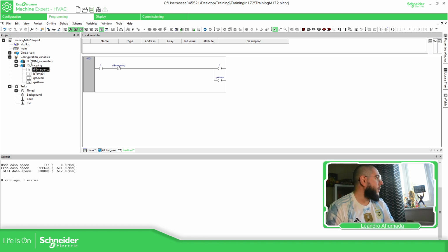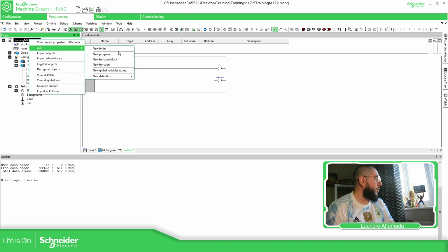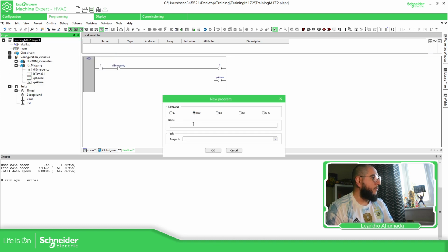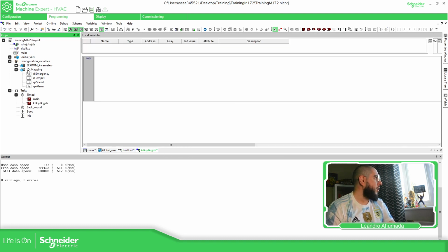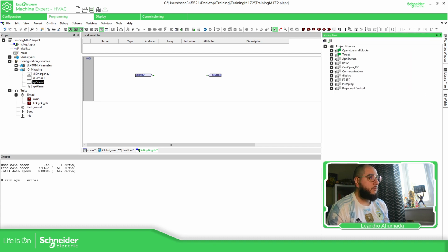So simple. Now the additional thing is that if you're using the FBD, time, it will depend on the input and output that you're trying to use, because you cannot write on the input, so you need to make sure about that. So temperature, input, and now, for example, speed, output, and there we go. Then in the middle, depending on the value, you just have a different set point. It's up to you using the PID and then have the calculation, but this is what you need to do.